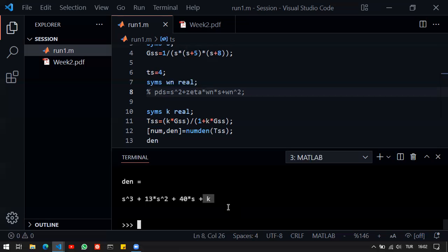So there's a bit of a challenge because we have 3 poles. This is a third order polynomial. And the only thing in the polynomial that we can change is basically k. So we're pretty much limited to k, and we're pretty much limited to the fact that we are only changing the constant term. Yeah, and all the other terms are not affected by the controller.